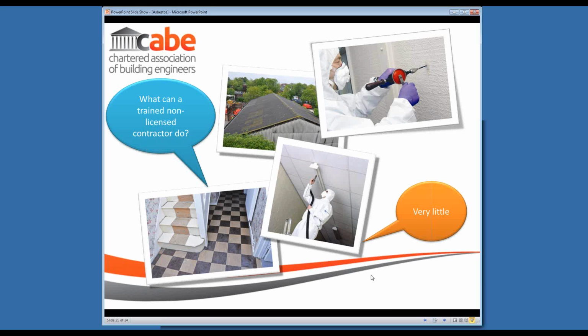So when you're looking at drilling holes, replacing light fittings that are fitted to asbestos tiles, taking up floor tiles, cleaning guttering, all of those things, although they could potentially be done outside the licensed framework, would realistically require the contractor still to be aware, to carry out awareness training, to provide the protective equipment, and to make sure that there's a method statement to address how the work's going to be done.